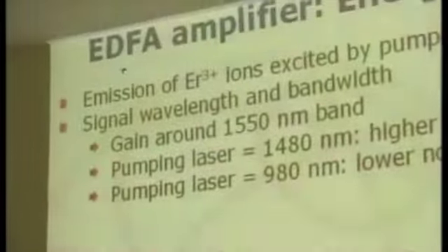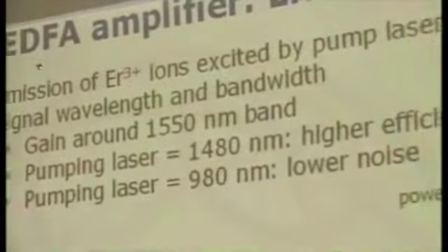If the pump laser is applied to the EDFA system, this is the energy level of the erbium ion. This excited state of the erbium ion will generate light. This is radiative emission, at nearly around 1,550 nanometers. And you will see such a broad spectrum noise as the output of the EDFA.